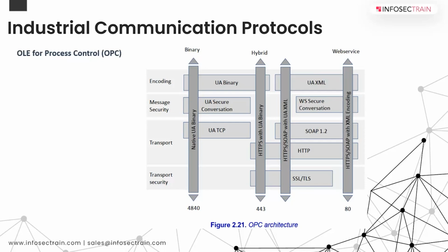You still would need a gateway device for that, unfortunately. So that is how it is. Like I was saying, OPC UA provides greater security to the architecture, so it is advisable to deploy OPC UA rather than the traditional version of OPC, which is a nightmare.